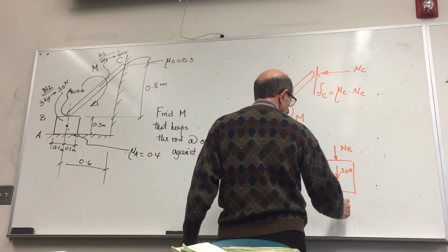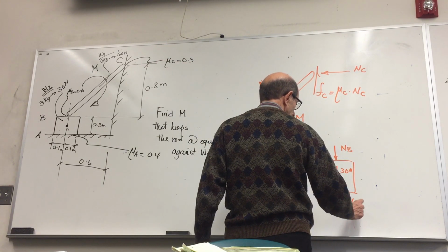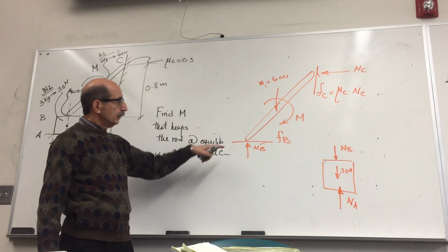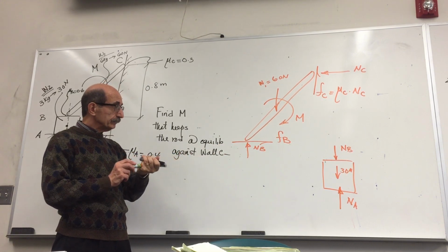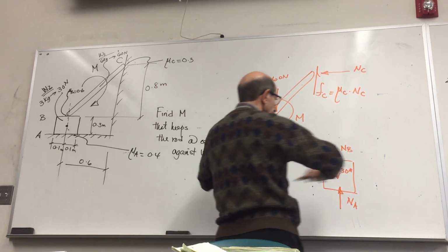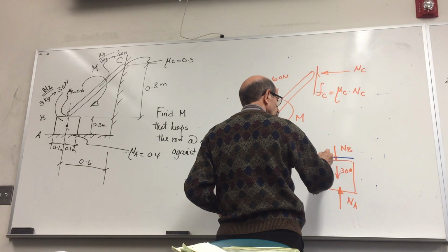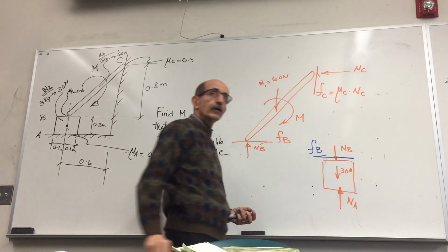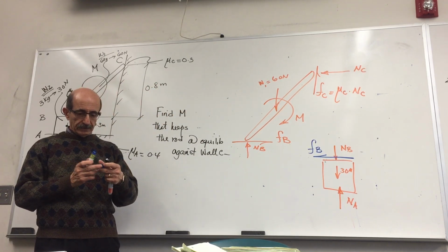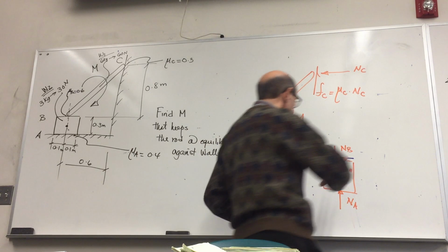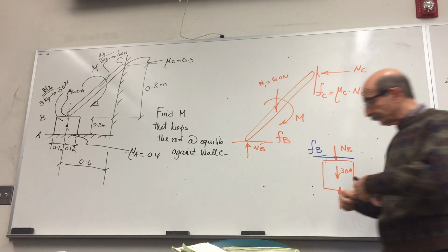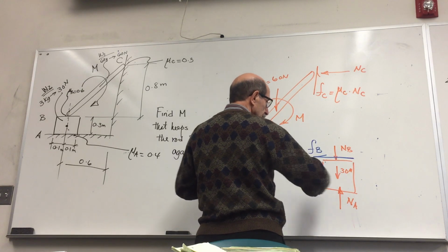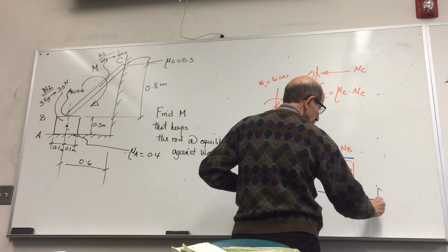And we have also a vertical force at A. But here, if this is the force of friction acting on this bar, on top of this box, we will have the force of friction acting this way, right? So that is the only force acting on this box that will have the tendency of moving the box that way, right? So the friction force then on the floor or along the floor should be in the opposite direction.